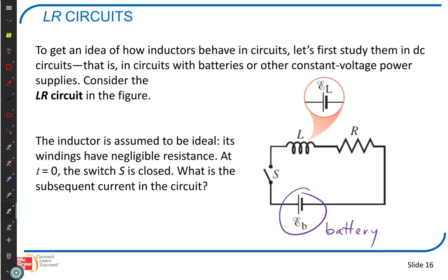With the inductor, we have a similar rule. We can't go from zero current to some random current. We can't have a discontinuous jump in current because that current is building the magnetic field. And you can't just go to a large current from nothing. So the current has to change continuously. So there is no current before I flip the switch. When I flip the switch, initially the current's zero, but it starts to flow. And so I'm going to have a current start to flow.